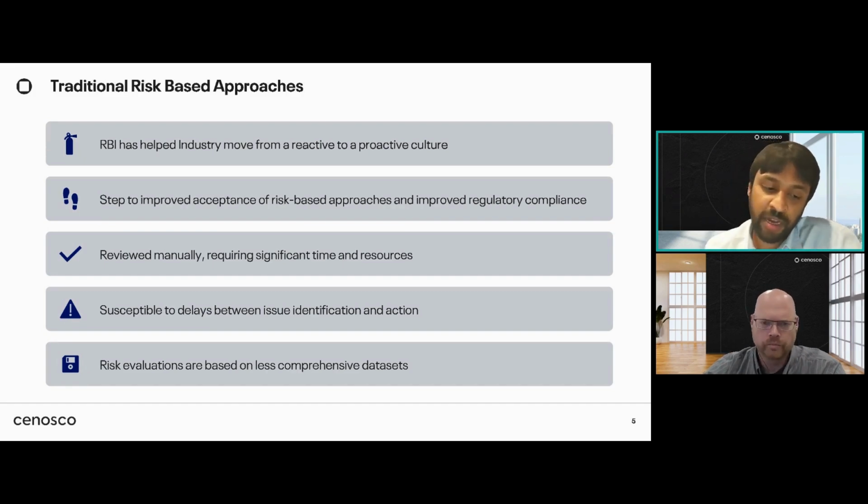Okay, you update your RBI 3 years back, but 3 years from today, things have changed. My degradation rates could potentially increase. So unless we revisit the RBI next time, that change in corrosion rate has not been really accounted for. And once we have better visibility with changes in degradation rates and things like that, that gives sites much more confidence in terms of incorporating appropriate corrosion rates as part of the RBI or risk assessments, and then drive future programs accordingly as well. Right.